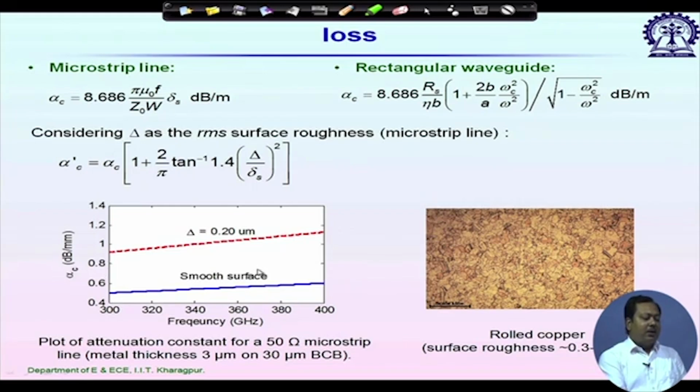So, that is why at submillimeter wave frequencies or even at millimeter wave frequencies, we can't use a microstrip line for long distance communication. Then what do we do? We use these printed lines like microstrip line or CPW line as interconnects for chip to chip connections, or from one component to another component connection, which we will be needing to design any millimeter wave circuits. So, let us take a short break, then we will start again. Thank you.